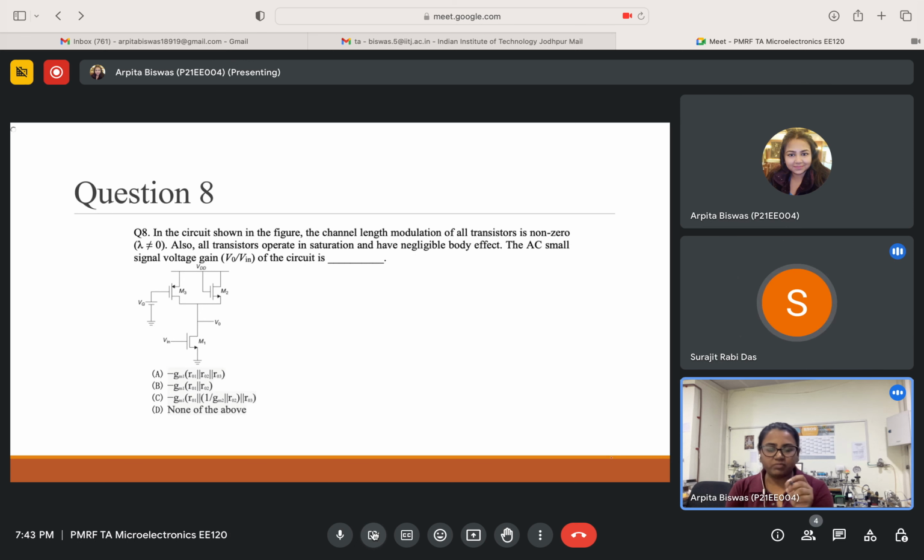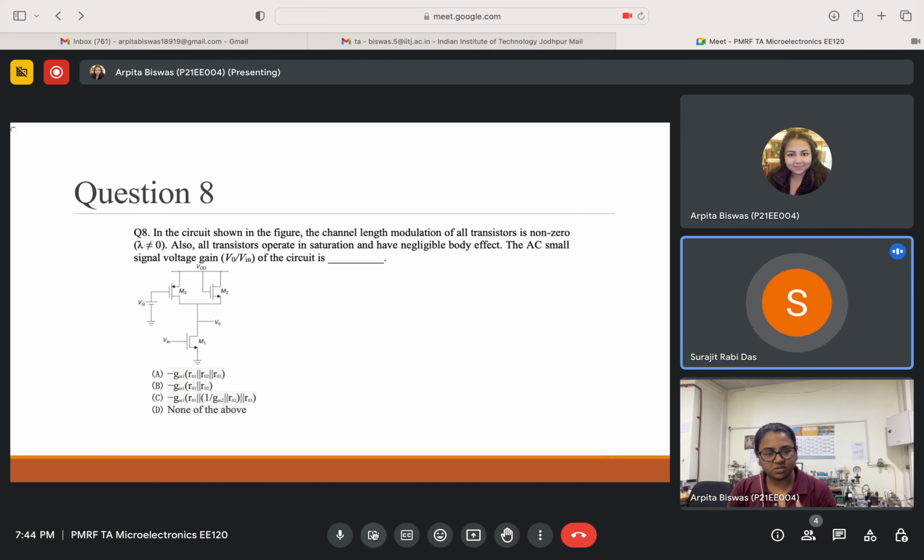Yes, yes. If there are two contacts, and between the two contacts the gap is micron size and your dust particle is also micron size, and you are not cleaning, what happens in that case? You won't get a proper device. Yes, correct, this is happening. That's why we have to clean properly, so that there is less dust particle or contamination. That's why we go through these cleaning processes.